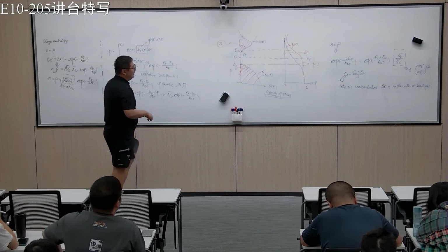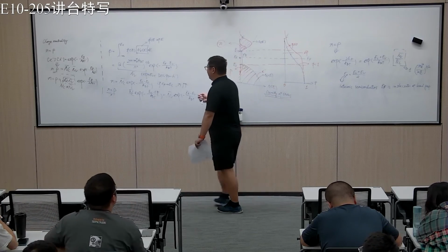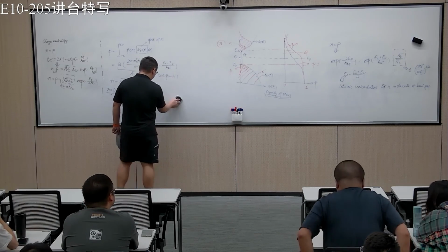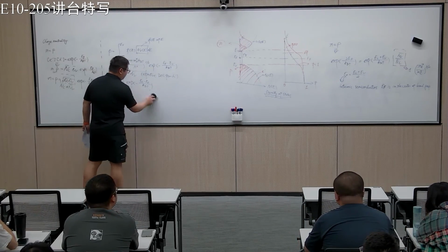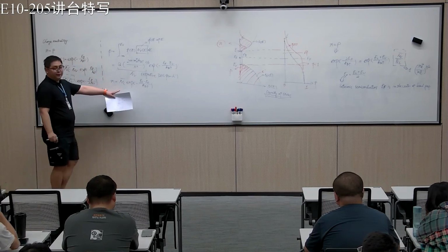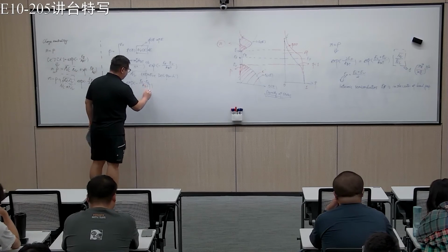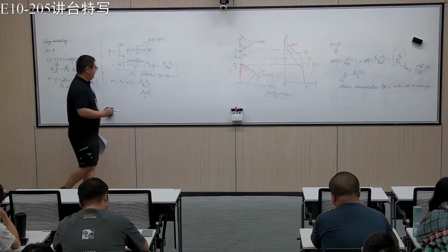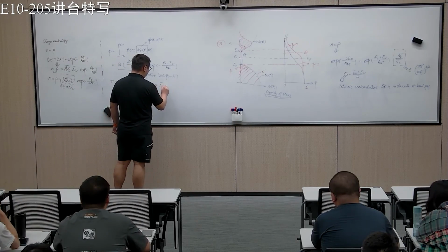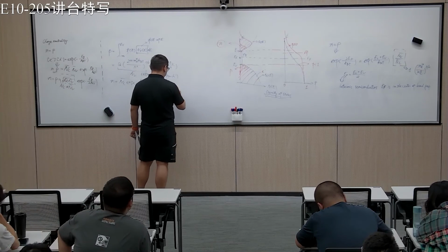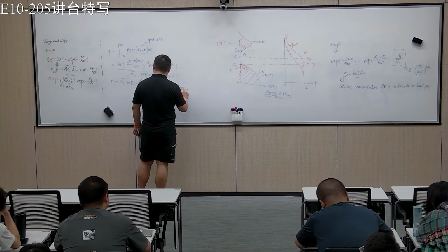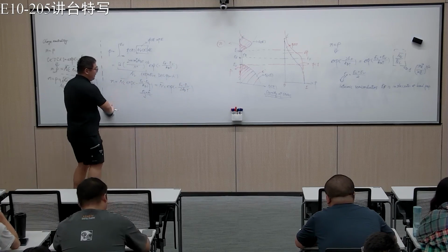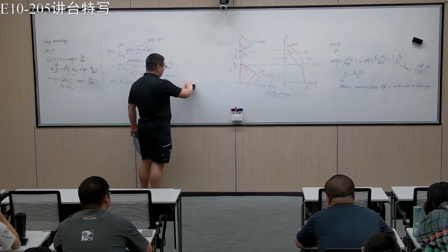So we finish by plugging this back into this equation. We know that now E_F is (E_C plus E_V) over 2. Then this guy is N exponential over k_B T, now E_C minus E_V, and we know E_C minus E_V is nothing but the band gap.